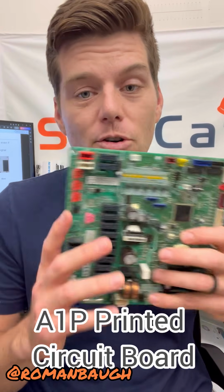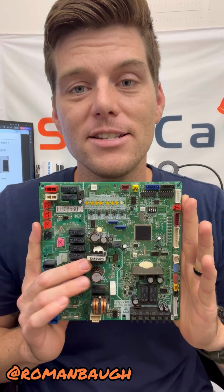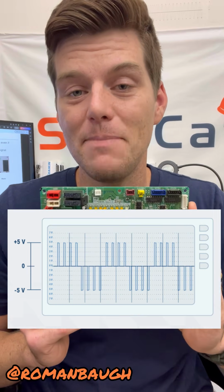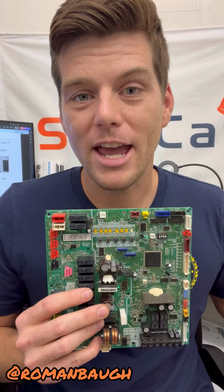You see, on an outdoor unit, just one-to-one, it generates 16.5 volts DC from this board, which is the carrier wave. On that carrier wave, it is sending plus or minus 5 volts DC packets to the indoor units, and back and forth they talk. That's how communication systems work.